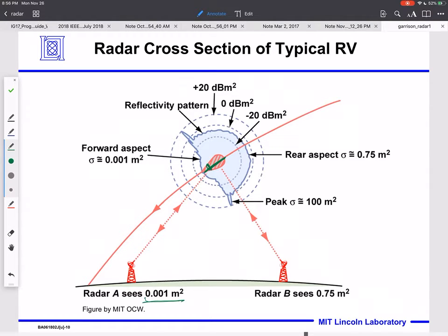So this is a typical type of measurement that could be made on aircraft, on spacecraft, on any type of vehicle, even on natural phenomena like snow, hail, raindrops, if you're wanting to measure those with radars, where we look at the scattering cross-section as a function of the geometry. And so again, this is a very common thing that's modeled, common thing that's measured. Obviously, if you're in the defense world, you'll want your radar cross-section to be small in certain directions. So that's a feature of geometry, as well as the type of material that the object is made of.